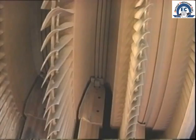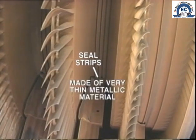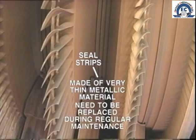Sealing strips are similarly used in other parts of the turbine where we need to eliminate or at least reduce steam leakage. A typical example is the interstage seals, which are on the inner circumference of the diaphragms where the shaft rotates. In all cases, the seal strips are made of very thin, soft, metallic material. They rub on the shaft and reduce the leakage as much as possible. Of course, as time passes, the sealing strips wear and need to be replaced during regular maintenance. We'll be discussing this aspect in another module in this series.